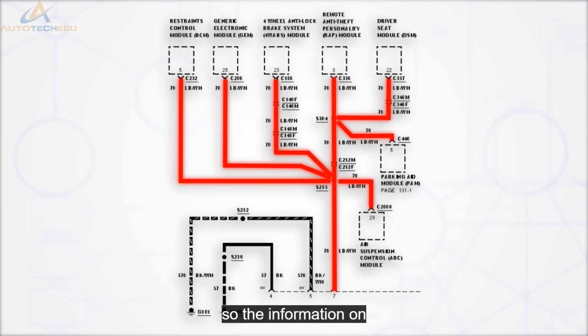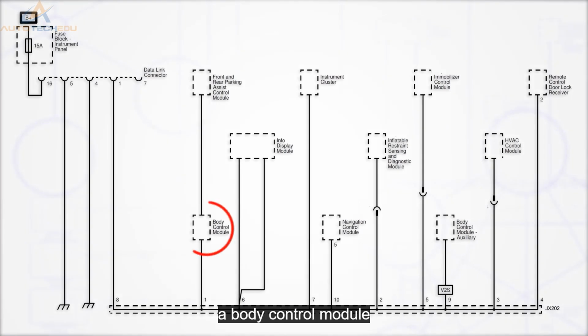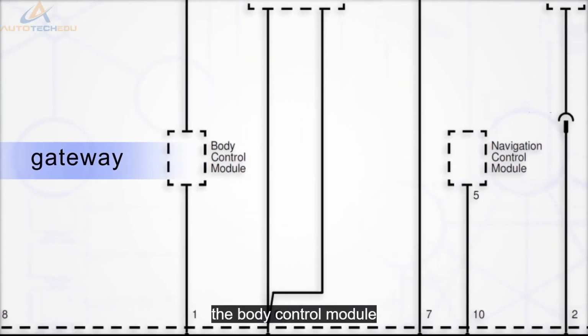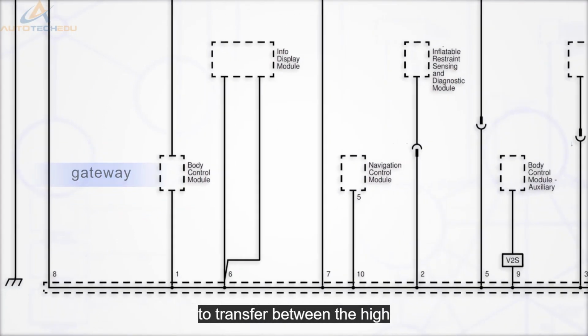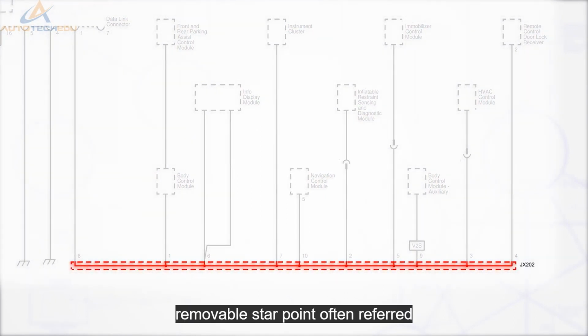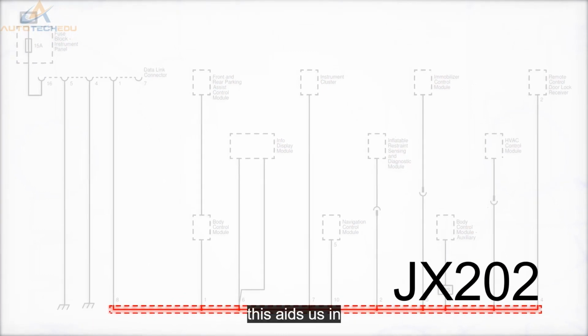So the information on the low-speed bus has no way of getting to any other bus. This is a star topology with the body control module being used as a gateway. The body control module can now allow data to transfer between the high-speed and the low-speed bus. There is also a removable star point, often referred to as a removable splice. This aids us in diagnosis.